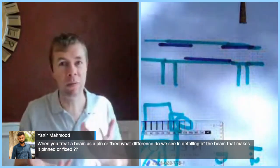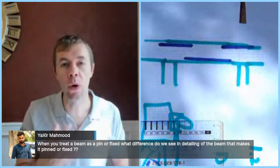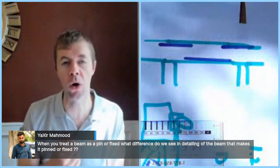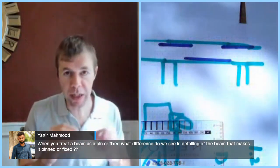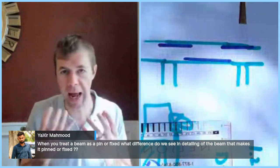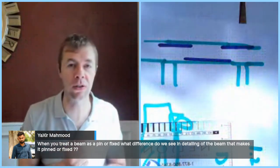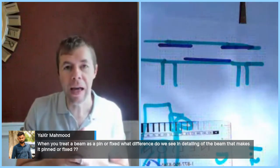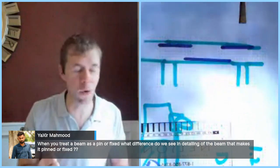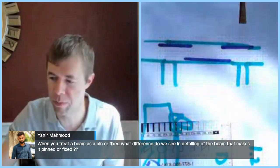And you might say, I know this is probably strange and hard to understand, but the more you understand, truly deeply understand about concrete, is that you can control where your loads go by where you put your reinforcement and how you think about your design. This is kind of the secret to something called strut and tie modeling. And with more study, you can kind of better understand how to handle these out of the ordinary situations. But I know that's probably a bad answer, but there you go.